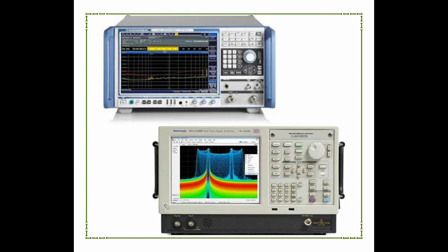Spectrum analyzers often offer more features than EMI receivers, such as the ability to measure signal modulation, perform vector analysis, and display spectrograms. EMI receivers, on the other hand, are designed to perform specific measurements such as radiated emission testing. While both spectrum analyzers and EMI receivers are used to measure electromagnetic signals, they have different capabilities and are designed for different purposes. A spectrum analyzer is used to analyze the frequency spectrum of a signal, while an EMI receiver is used to detect and measure electromagnetic interference.